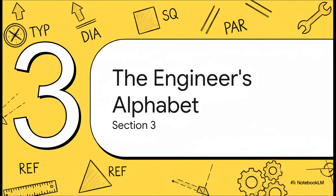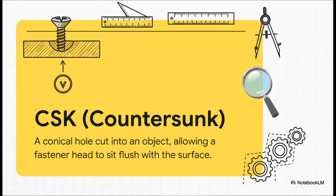All right, let's start decoding this thing. And just like with any language, you gotta start with the alphabet, the common abbreviations and symbols you're gonna see on pretty much every single drawing you ever look at. First up, we've got CSK. That stands for countersunk. It's a super common note that basically tells the manufacturer, hey, I need you to cut a cone-shaped hole here so that the screw head can sit perfectly flat with the surface.